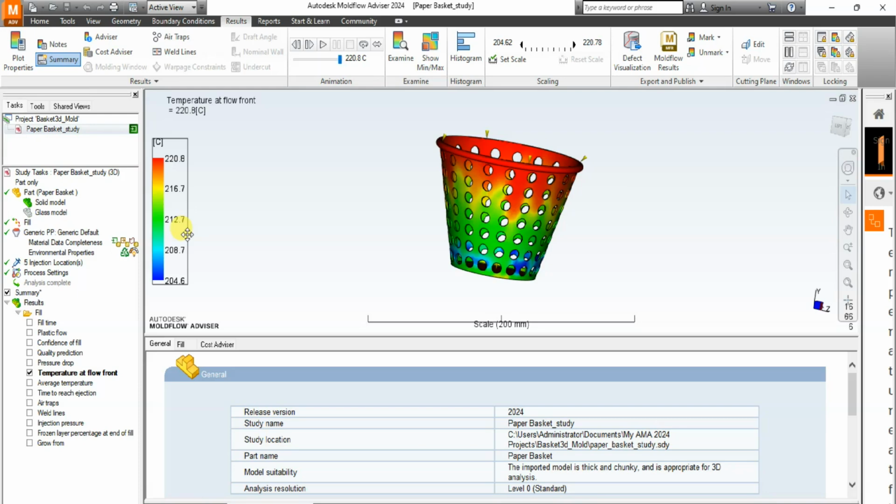if it is restrictive. Too much shear will cause degradation and surface defects. Now, you can also increase the melt temperature, and this may increase cycle time. It may also cause material degradation. Also, you should take note that you should keep the temperature within the temperature limits, as far as the flow front temperature is concerned. Then you can also use the specified material information in the database to take note of the variations, the optimal values for the existing product, the model.